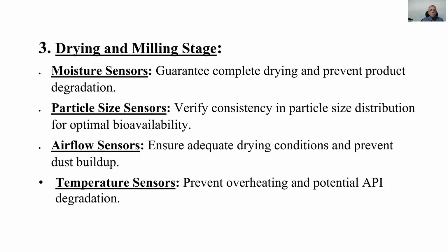The next stage in API is the drying and milling stage, where you want to monitor the moisture content. Moisture sensors guarantee complete drying and prevent product degradation. Then there are particle size sensors, which verify consistency in particle size distribution for optimal bioavailability.